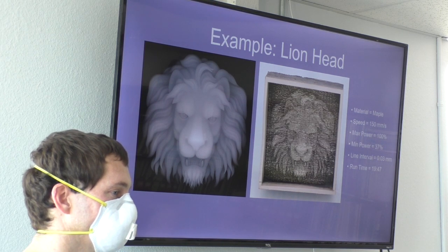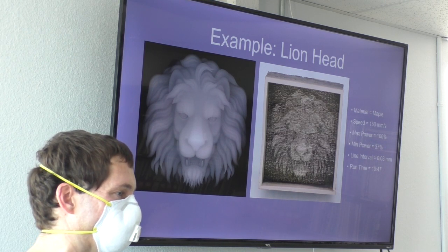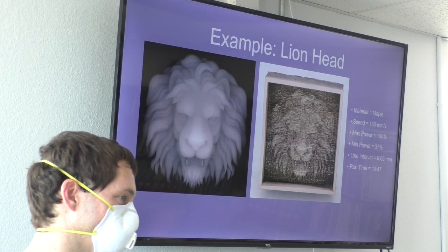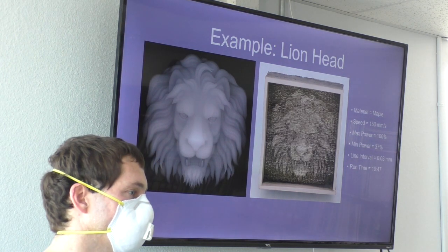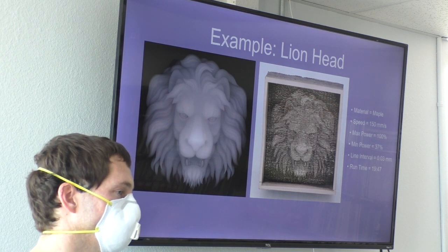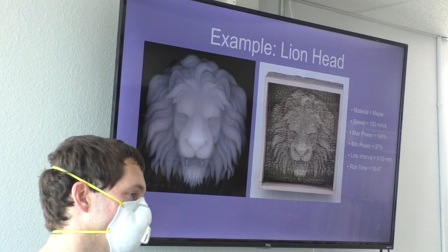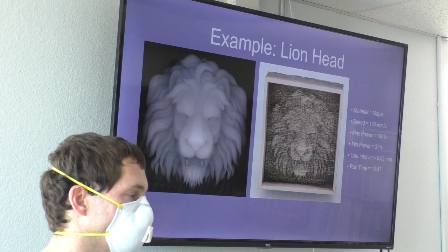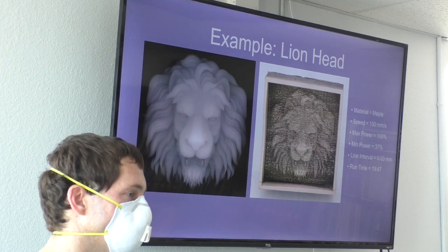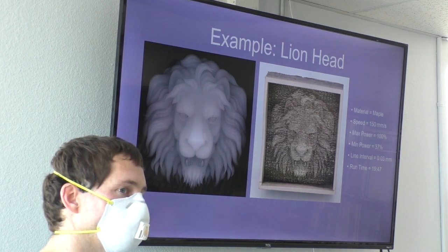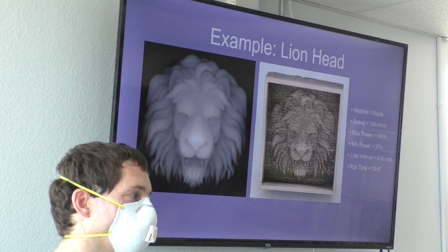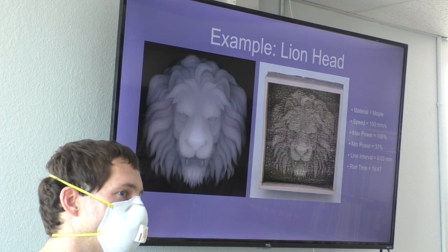If I wanted to cut it out, I had to cut it out on the CNC and then do all the engraving and stuff for that thick of wood. I'm actually finding anything over about 1/4 of an inch with the lens that I have, and I don't know whether you have the same issue here. You can see where the focus of the lens is changing, and although it burns cleaner than the 3/4 inch, you can definitely see the incline or angle on the edge of that piece of wood.